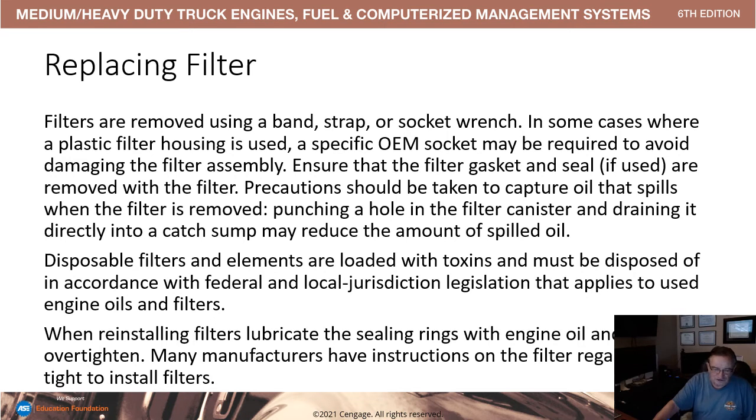And always check to make sure that the flange base has all of the O-rings off it. It is possible to double ring, to install a filter where an O-ring is stuck on the flange, and that would cause serious loss of oil and potential engine damage.